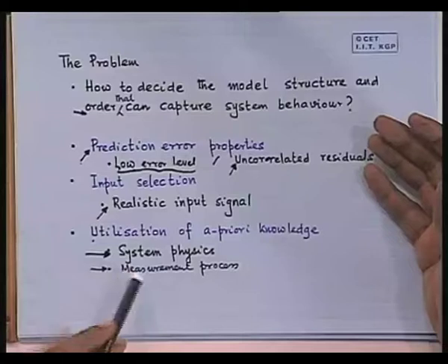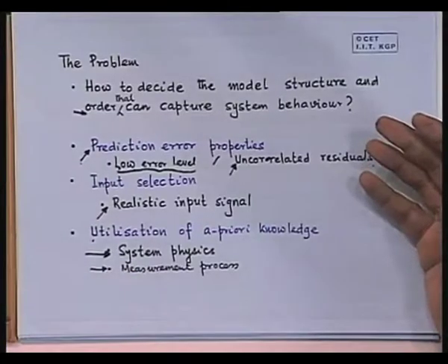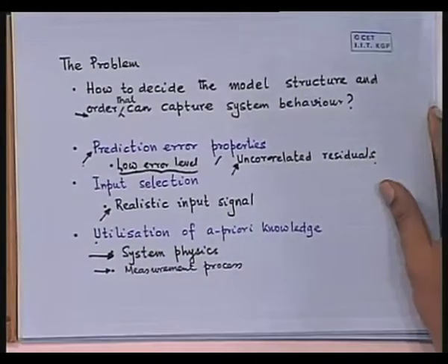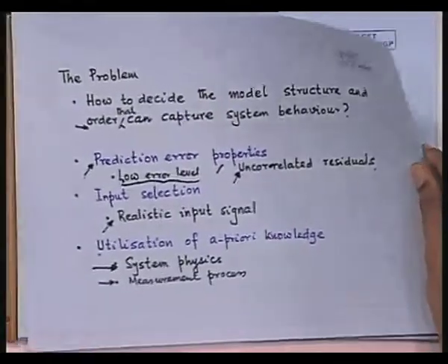As far as you are using a linear system model, whether you are using difference data or sum data, as long as you are doing linear operations on the input, the model remains the same, almost, right? So you may like to estimate your model based on difference data. Such knowledge has to be used when you are doing the model order selection.